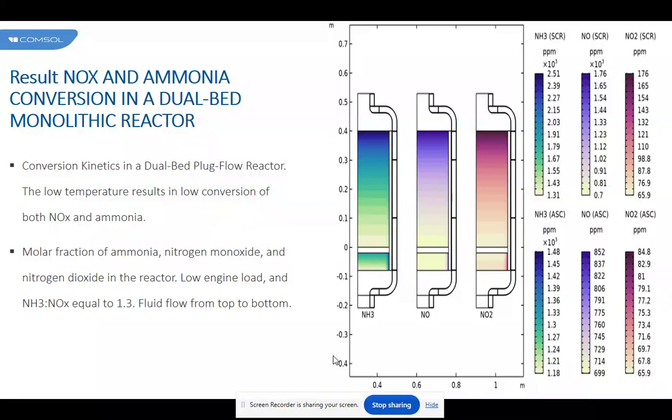The fluid distribution in monolith type converters has been extensively studied over the past several decades, both experimentally and using computational modeling with various geometries and transient conditions. Some studies have specifically looked at the effect of fluid distribution on the light-off performance. Other studies have modeled efforts to alter the fluid distribution using fluid tailoring devices.